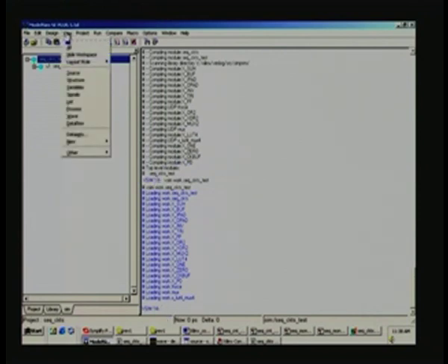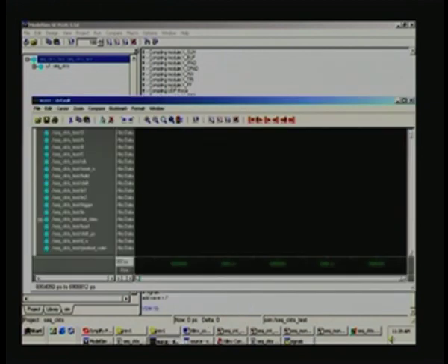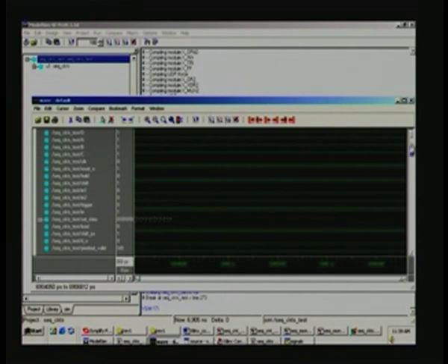The next step is to see the waveform, for which we can use View, then Signals, and when the signals window opens, you use View Wave, and the last option is Signals in Design. This is what you are already familiar with, and it's already open here. Now what we need to do is run this. It has run, and once again this is crowded here, you can't make out anything here.